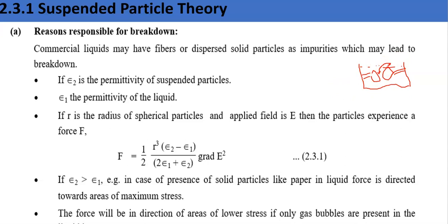Imagine chalk dust is there, or some fiber, or some paper fiber or cellulose. Now, what will happen? You are applying a very high electric field across the electrodes. As a very high field is applied, here it is the electrostatic forces. These particles which are suspended are very light and free to move, so all this force will be exerted to bring them into the gap between the electrodes.